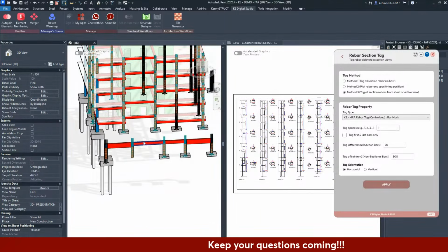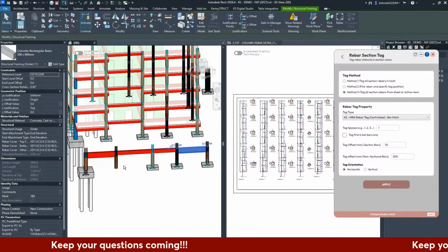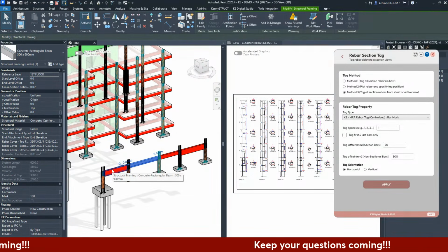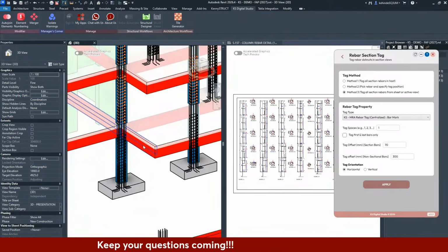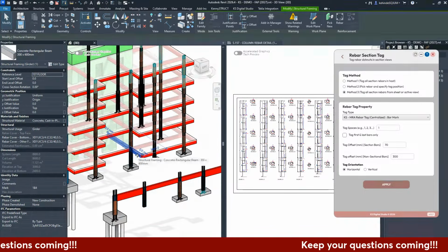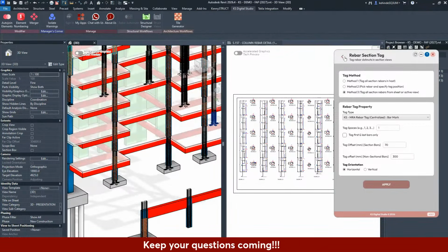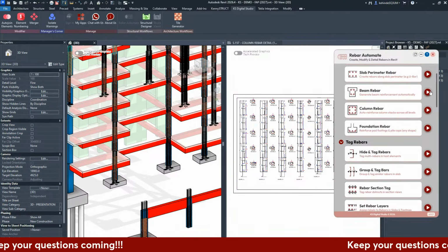It's amazing. We also created this situation where you have multiple beams. So it captures collinear multiple beams broken at the column supports. You can also sort out your cantilever bars, and cantilever beams have been captured. And you can also merge bars of two different spans together.